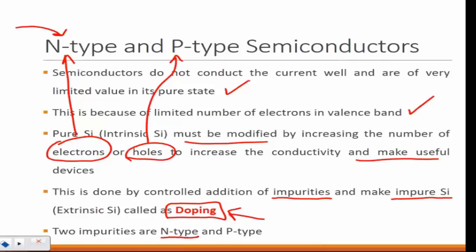When we say N-type material, that material is very rich in electrons. Since electrons are negatively charged particles, the N implies extremely high electrons. The number of electrons is very high compared to the number of positively charged. The term used is majority charges. In N-type, the majority is electrons and the minority is holes.